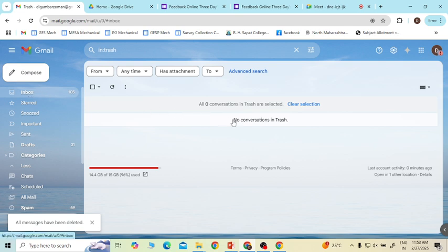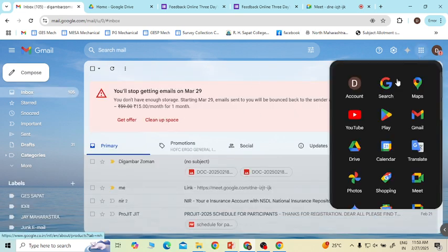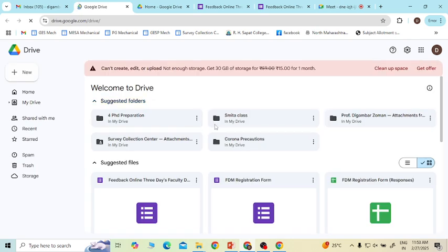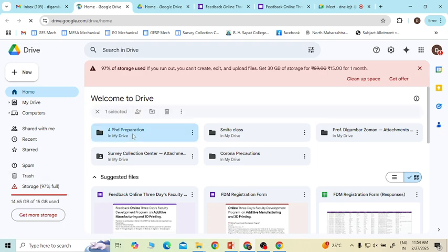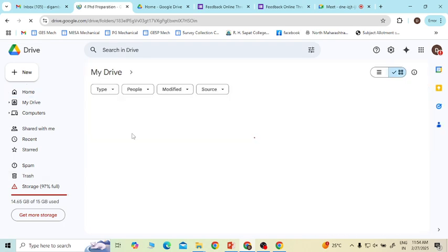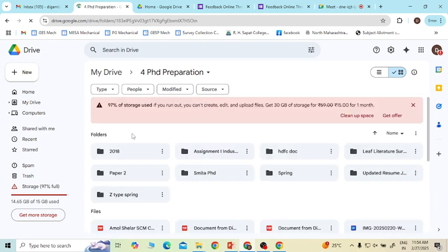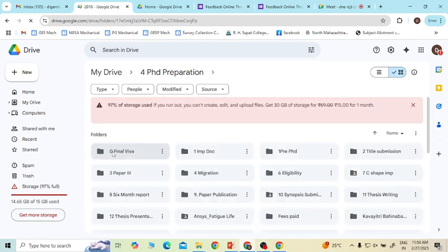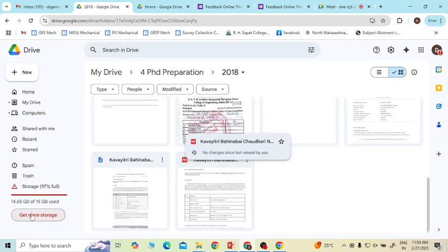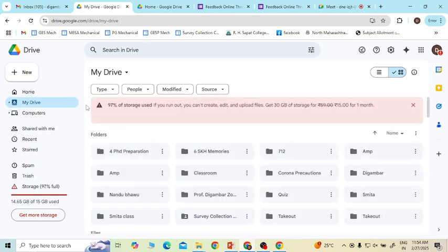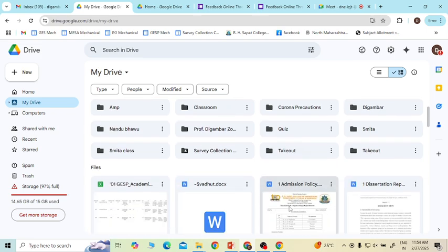For the next layer, the table will come down by a distance equal to the thickness of one layer. The additional resin will be there, and it will be cured, and likewise. So there are layers of solidified resin, the first one, the second one, and so on. When it is to be cured or solidified, the laser will be focused on this particular area. This is Z, and on the XY you can have any geometry of that layer. This is basically what stereolithography does.